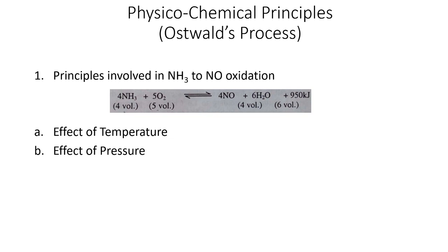What happens is, these reacting gases, the reactants, are gases. So if you increase the pressure, the space velocity, that is the volume of gas corrected to normal temperature and pressure conditions which passes over 1 cubic foot of catalyst per second, means the quantity of gas exposed to the catalyst increases.